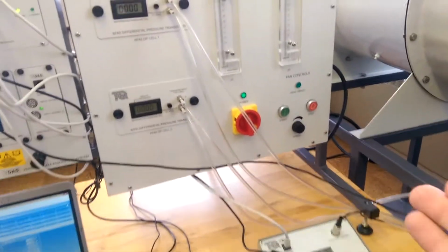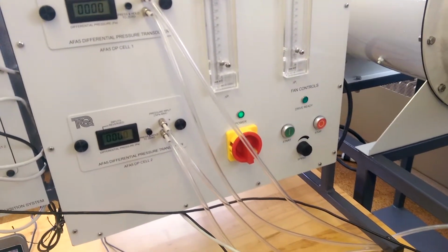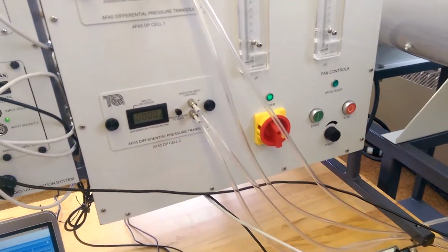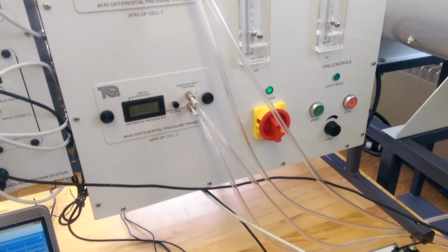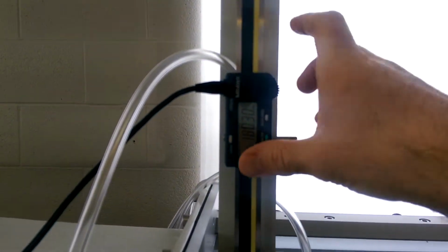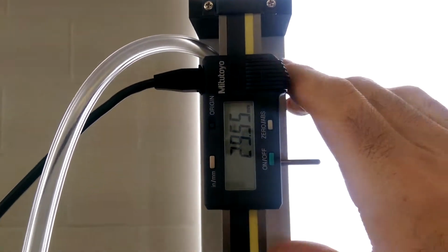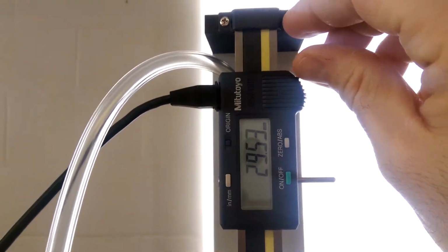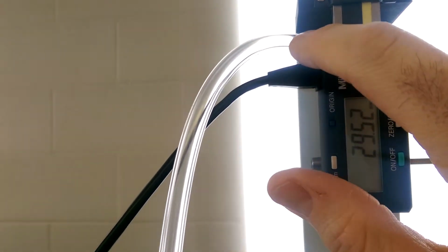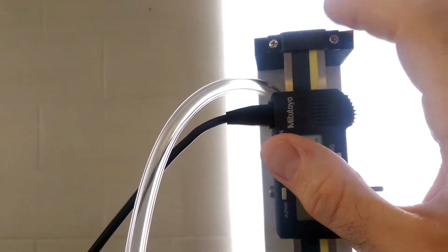So now you're all set. What you're going to do is turn on the wind tunnel to a velocity of 25 meters per second. Once you do that, move the pitot tube almost to the top, but not quite. So this actual device here is just slightly below the topmost position, so that you don't get the tube here caught up in between the top and the point at which it connects to the pitot tube.